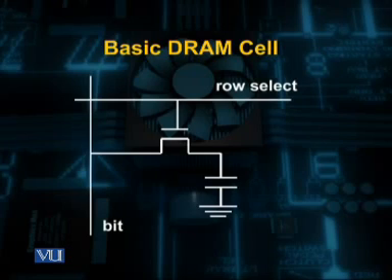This will basically cause a small voltage change on the bit line, and a very sensitive amplifier is therefore needed to measure this small voltage change with respect to the reference line. Once again, the value we stored will be destroyed by the reading operation, so an automatic write-back circuit is to be included so that the memory read operation is not a destructive operation.